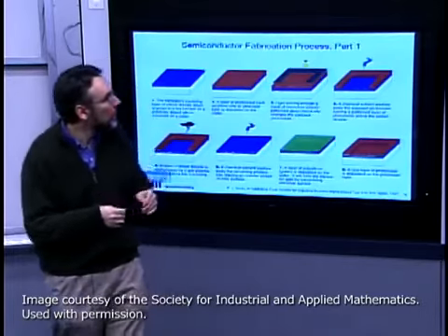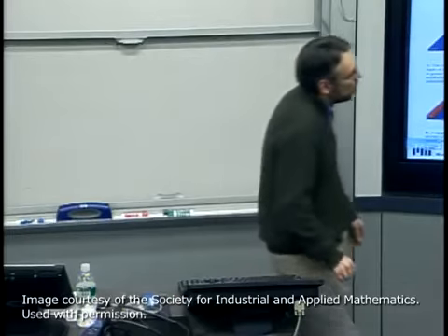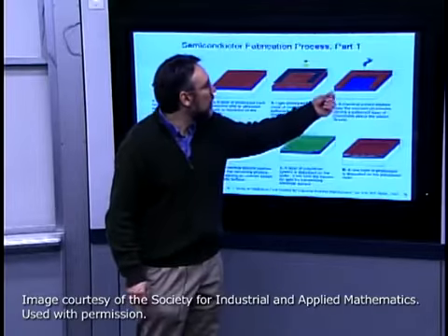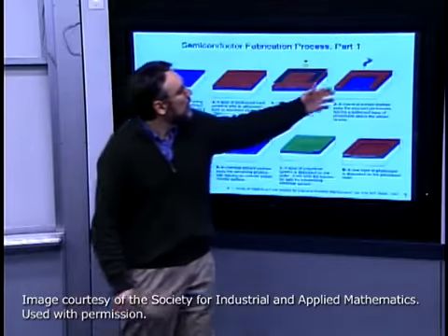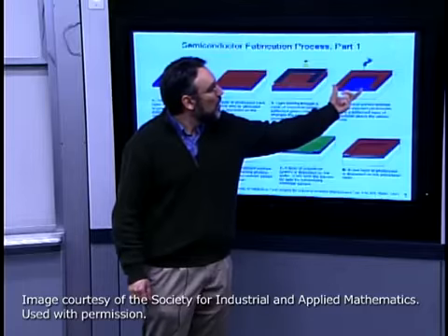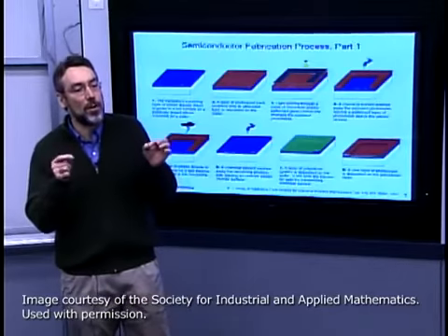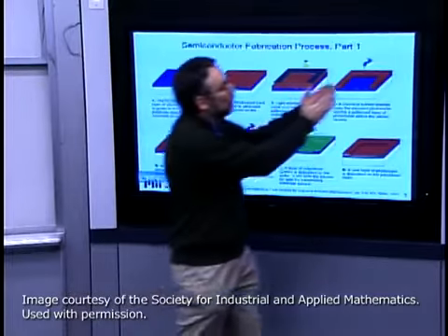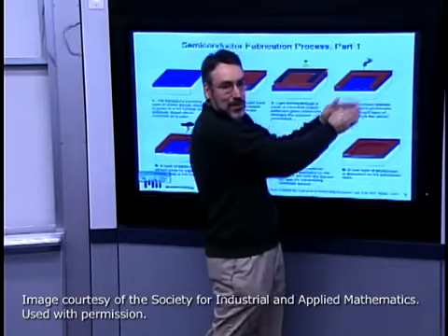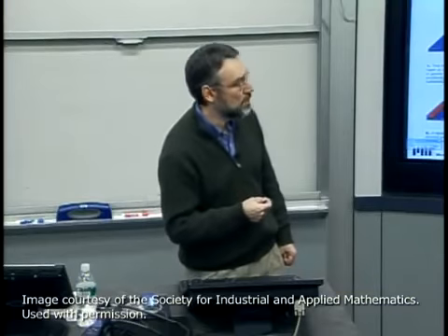exposed. Okay, so actually there's some degree of design choice in picking positive and negative photoresist depending on some manufacturing control issues. It turns out if you're developing away material, you might, in one case or the other, be able to actually overdevelop or overexpose slightly and control slightly the line widths of these features a little bit better in one photoresist case than the other, depending on what you want to do.